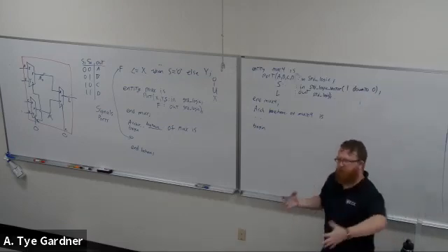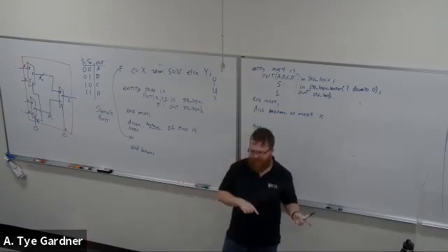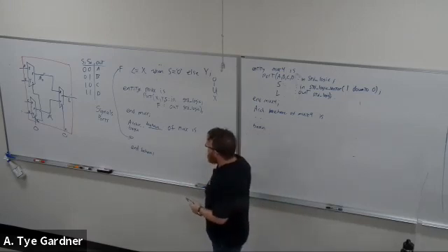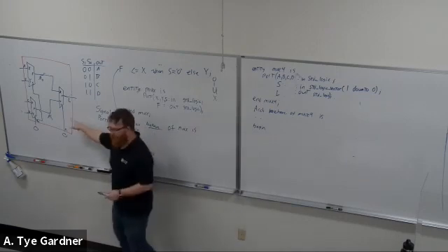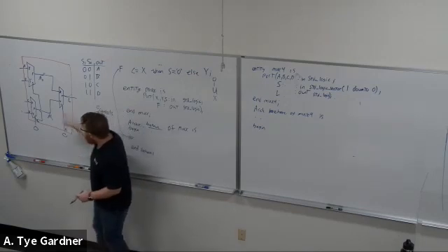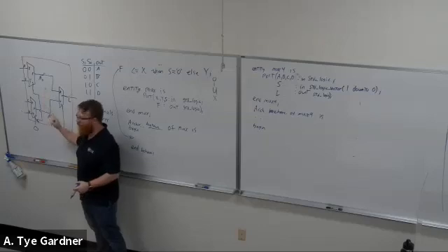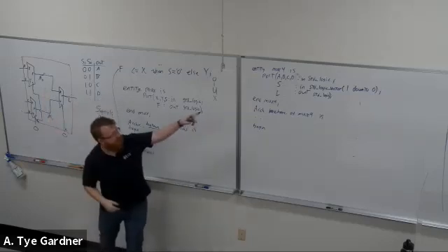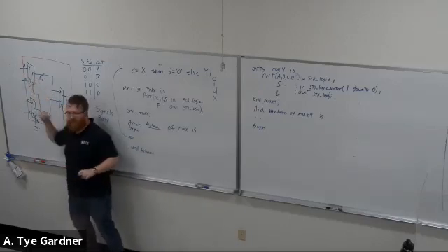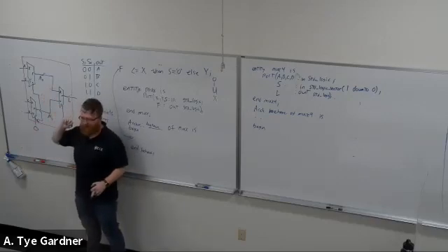The next thing I have to do, remind you guys that VHDL, like most programming languages, doesn't know things exist until you tell it they exist. I'm going to need to tell it both, because this is the red box I'm going to build. I need to tell it that the mux exists, and that the signals that connect them together exist. Because when I create the entity with A, B, C, D, S, and L, it makes the ports for me, but these connecting signals aren't ports, they don't exist yet.